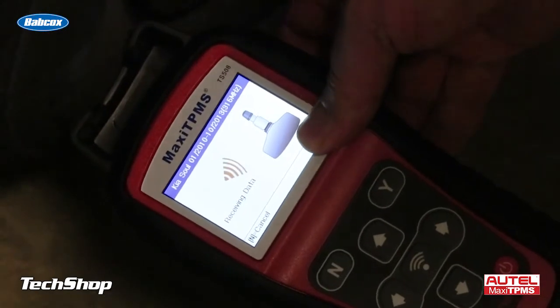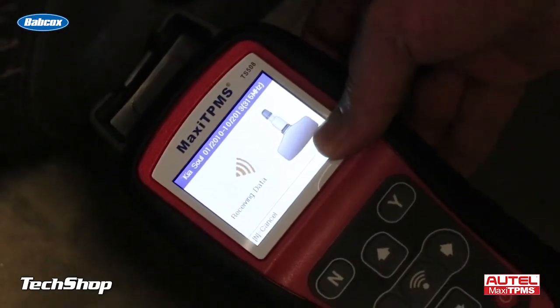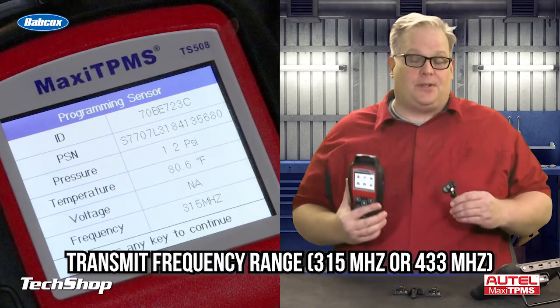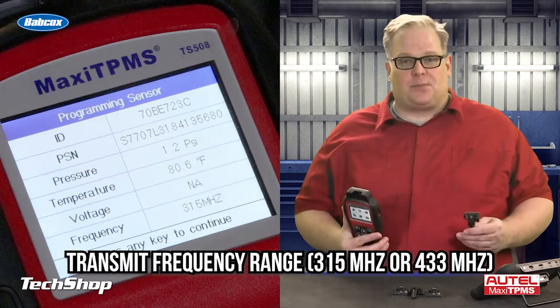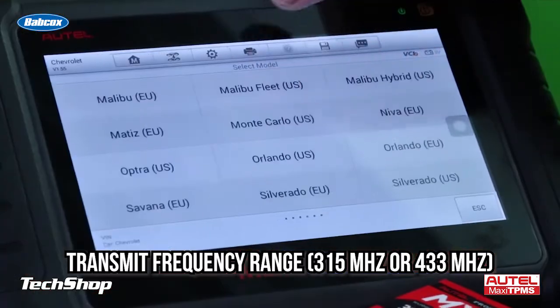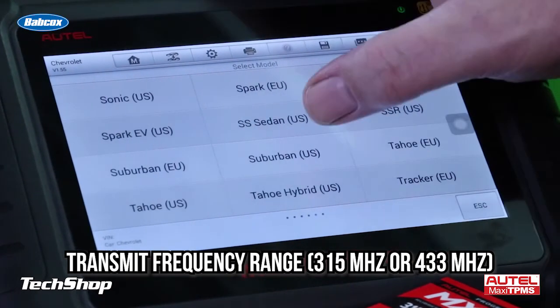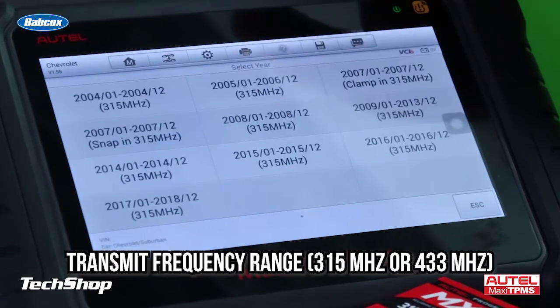The protocols that a TPMS sensor has to do to transmit the tire pressure to the vehicle change depending on the make, model, and even year of a vehicle. What a universal programmable sensor can do is replicate those protocols by programming it with a TPMS tool so it can communicate with the vehicle. One of the first things that gets programmed into the sensor is what frequency it's going to transmit at. About 96% of the vehicles out there transmit on two frequencies, 315 megahertz and 433 megahertz. There are some oddballs out there, but they're very few and far between.